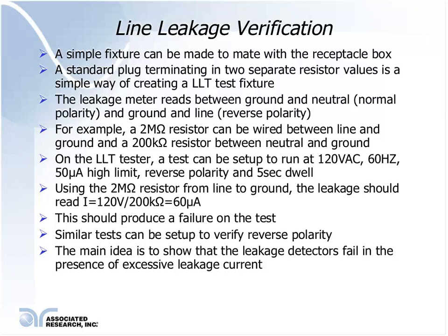A line leakage tester also contains various other relays. The main idea here is to show that the leakage detectors on the instrument fail in the presence of excessive leakage. That is the most important thing to verify here: that the detectors on the leakage tester are failing in the presence of excessive leakage current.